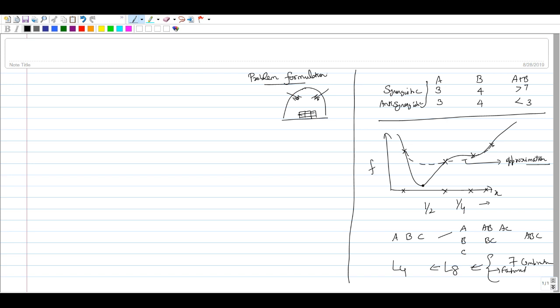So in order to be able to do this, there are different ways in which you can look at formulating. For instance, one way would be to minimize your variance or maximize your SN ratio, which is equivalent to it, because this noise is represented by your standard deviation.